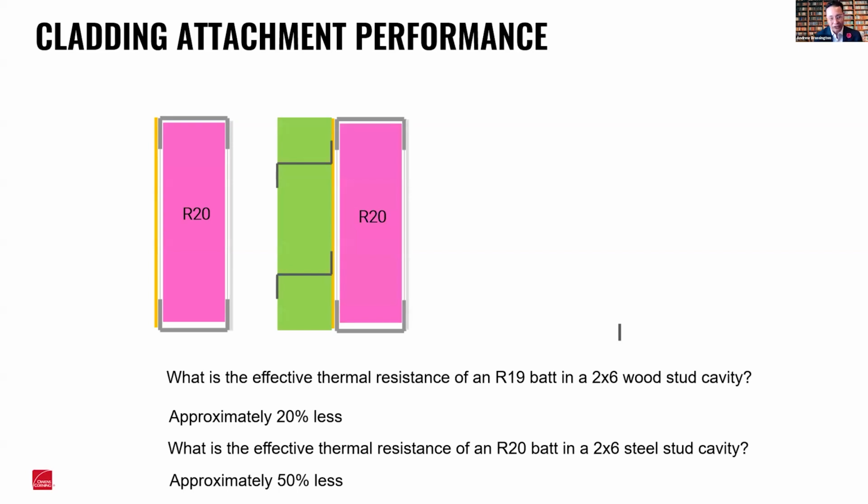Then we started to go to exterior wall insulation, and we went to a girt type system. As you can see, these lines right here will show a girt system. There's no insulated clip or anything like that. It's just steel on steel. Well, this sometimes had the ability to conduct or continue the thermal bridging. So you potentially will see 50% of that R value on the exterior wall deteriorate as well. So you might have put 5 inches of exterior insulation, but you're probably only getting approximately R value for about